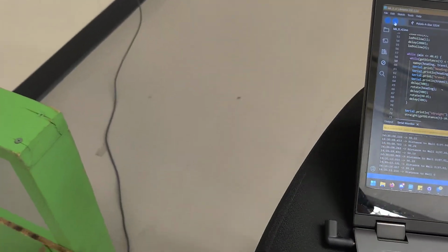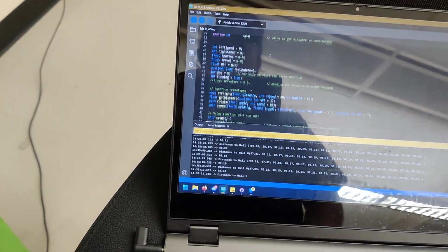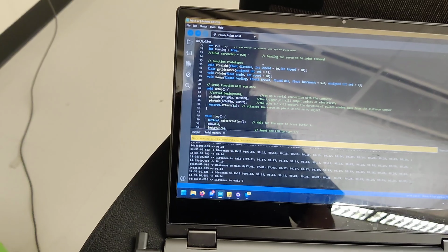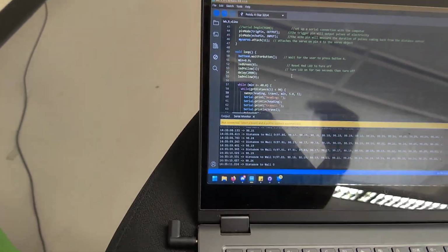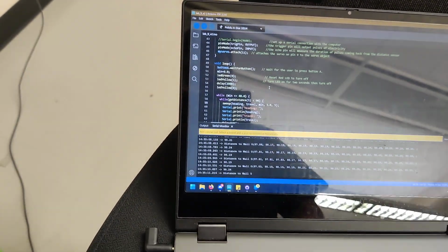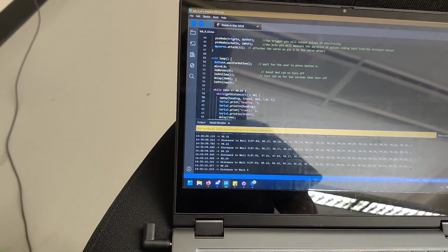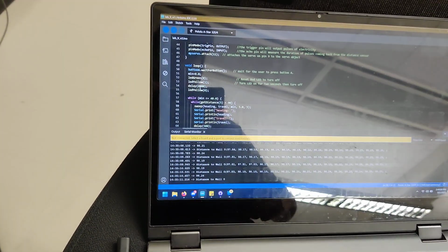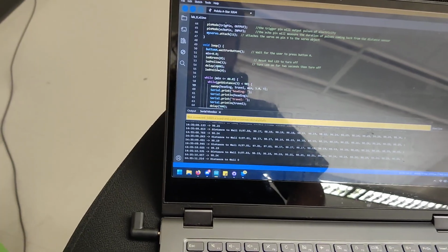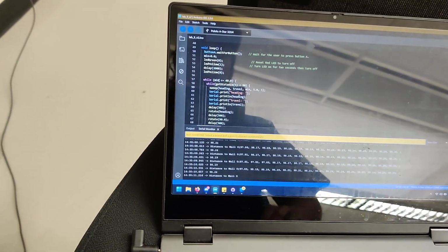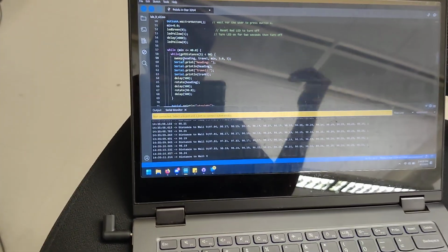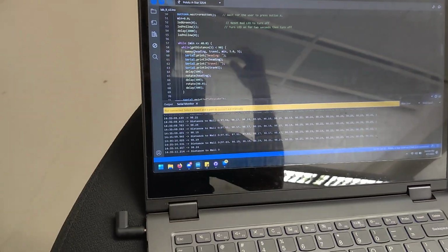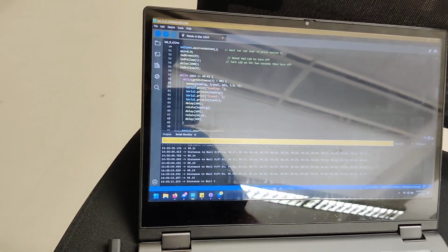Alrighty, for a quick run through of what our code does, a bunch of initialized variables and stuff. This has to get cleaned up later on. But in our void loop, we wait for button A. Turns on, it resets our variables, goes ahead and turns off our green LED if this is not the first iteration of this loop. And then pauses for 2 seconds as required, and the yellow LED is just for debugging, which will get eliminated later on. So our initial while statement is while our minimum distance found by the scan is less than 40, it will run to continue staying in this loop.